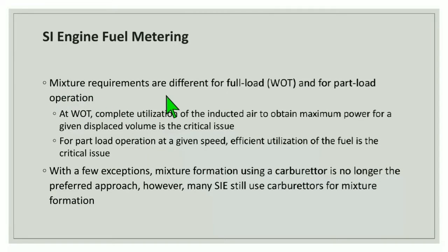Mixture requirements are different for full load and for part load operation. At full load, complete utilization of the inducted air to obtain maximum power for a given displaced volume is the critical issue. For part load operation at a given speed, efficient utilization of the fuel is the critical issue. With a few exceptions, mixture formation using a carburetor is no longer the preferred approach. However, many SI engines still use carburetors for mixture formation.